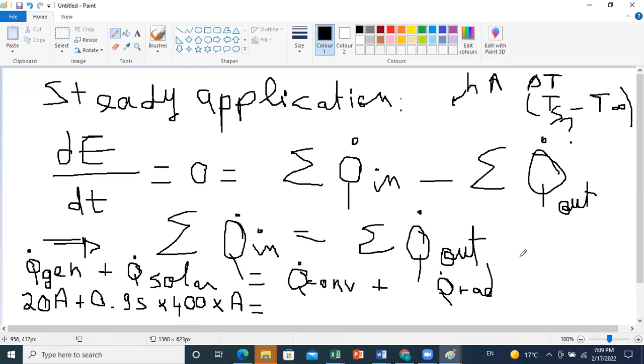And we'll see that in radiation, TS should be in Kelvin. So please, you should verify that TS is in Kelvin everywhere. So this is very important. If you put T infinity here in degrees, this means that TS should also be in degrees. And since you are dealing with the same variable TS, you cannot put it in certain terms in degrees and in other terms in Kelvin. This will give you a confusing value at the end. Okay, so to be on the safe side, because in radiation you need to use the Kelvin unit, you should keep all temperatures in your equation in Kelvin because TS is unknown. If it was given to you, it's fine if you replace it here in degrees, but then T infinity will also be in degrees, because delta T in degrees and Kelvin is the same.